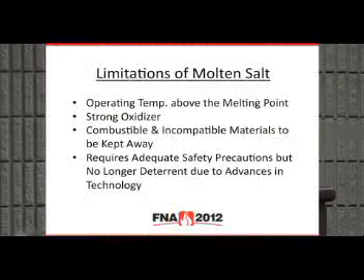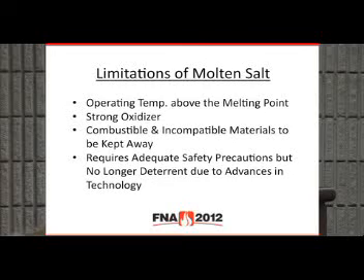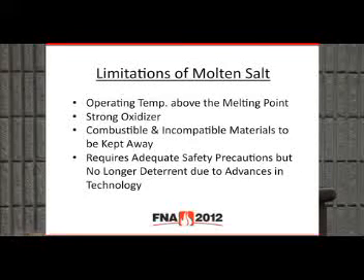It does have limitations, and obviously one of the limitations is you have to use it above its melting point, so you can't use it at lower than the melting point. And combustible and incompatible materials should be kept away from the salt from a safety point of view. And it does require adequate safety precautions, mainly because of the temperature. But most of the safety concerns have been addressed by the advances in molten salt equipment. So they are no longer considered a deterrent for the use of salt bath quenching.